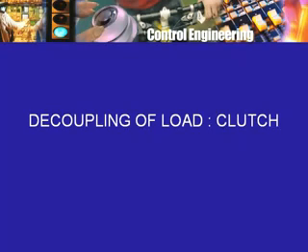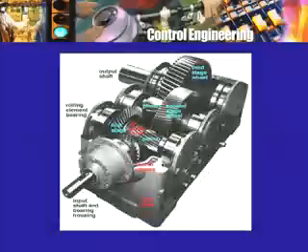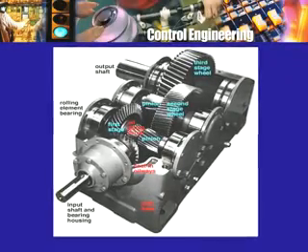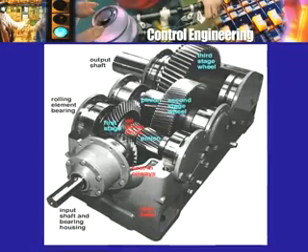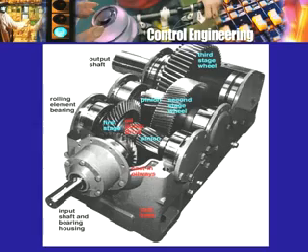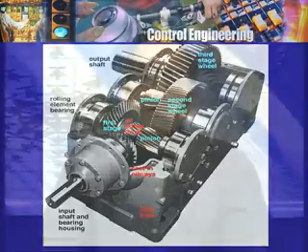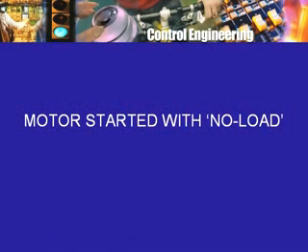As you know, in an automobile or in a scooter, there is this arrangement of decoupling the engine from the wheels, because there is a clutch. Of course, in those cars or scooters where there is a gearbox, there is also a clutch. So this arrangement is usually there. The mechanical load is not just left connected on the shaft all the time, but there is an arrangement for detaching it whenever required. So what one will do is start the motor with no load, as it is called.